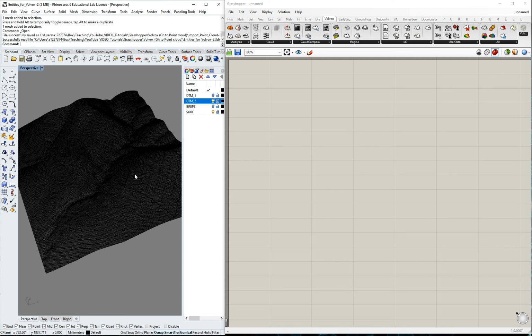So you need to find a common workflow that allows you to overlap them. A potential option could be importing all the point clouds using Volvox, aligning them so that whatever you have created aligns perfectly with the imported LiDAR point cloud, and then exporting all together as a new file. Make sense? So that's an option.